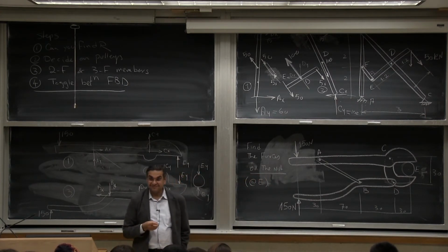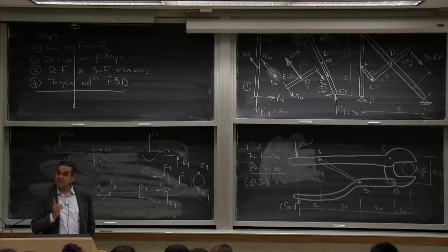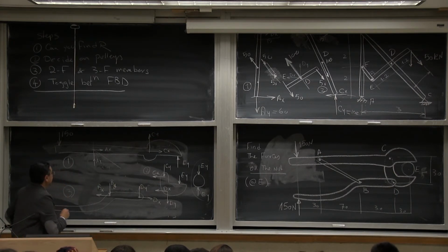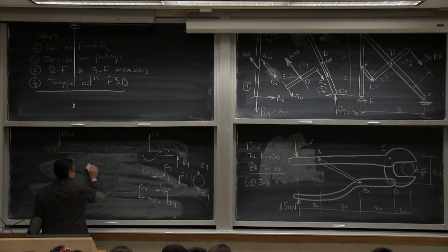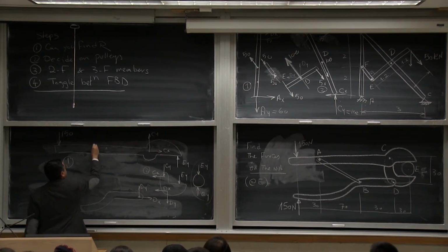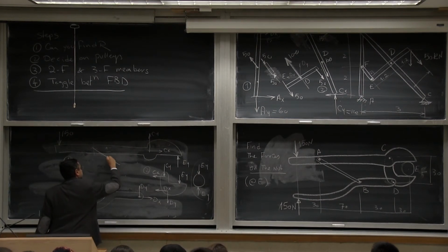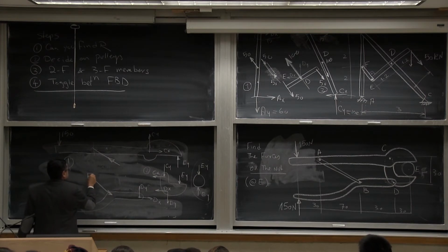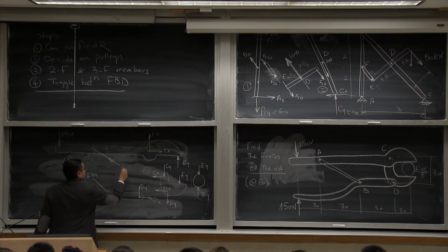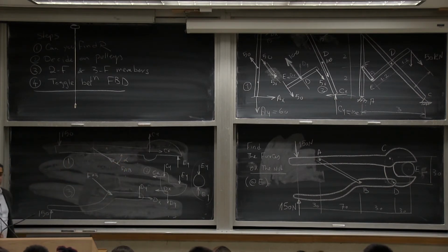Isn't it AB, a two-force member? Yes. AB is a two-force member. That's the key to the solution here. And most probably AB is in compression.